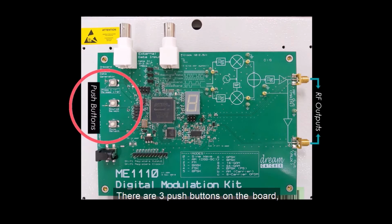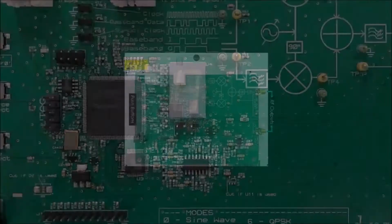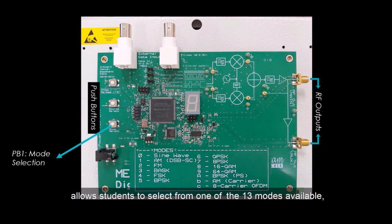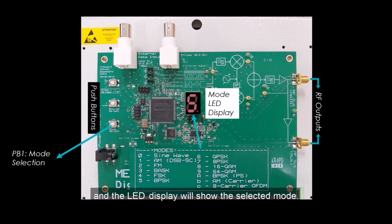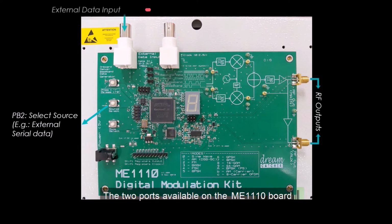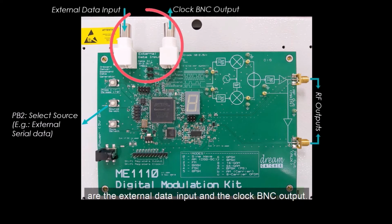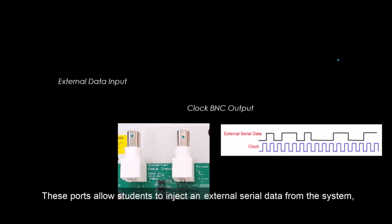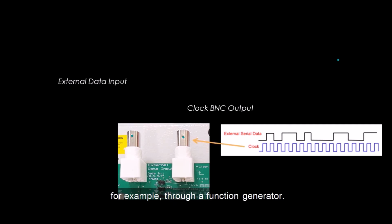There are 3 push buttons on the board. For instance, push button 1 allows students to select from one of the 13 modes available, and the LED display will show the selected mode. Next, push button 2 provides students the flexibility in selecting the data from an external source. The 2 ports available on the ME1110 board are the external data input and the clock BNC output. These ports allow students to inject an external serial data from the system, for example, through a function generator.